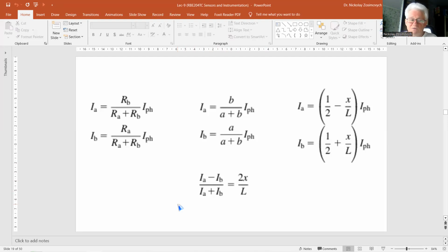The photocurrents vary analogously with the position of the incident light beam. And this is one of the reasons why researchers have designed PSDs with on-chip analog signal processing to accomplish intensity-independent output signals according to our last equation.